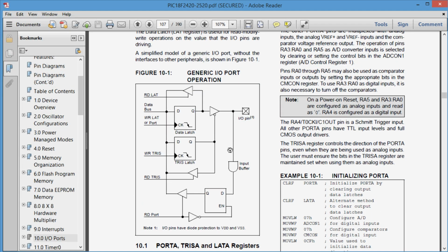There are slightly different ways in the definitions, but if you look at any microcontroller, in fact any kind of microprocessor or CPU type device, this is how it's done in them. Some of them, like the Intel devices used in your PC, are much more complex than this, but the same basic idea is used. You can assign the pins to be an input or an output by much the same method. Just on an Intel device, the data bus is 64 bits wide, and there's a whole lot more going on inside them.